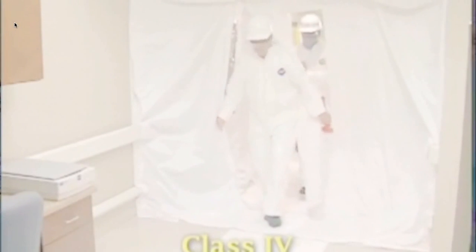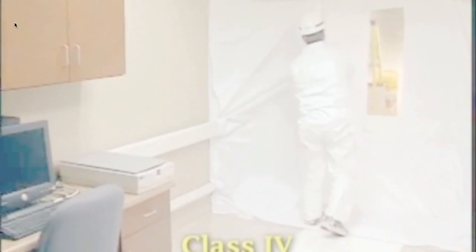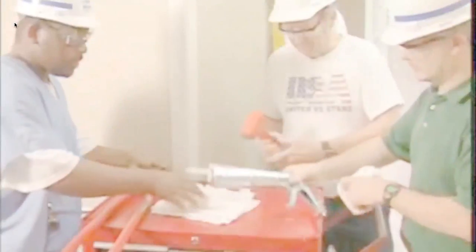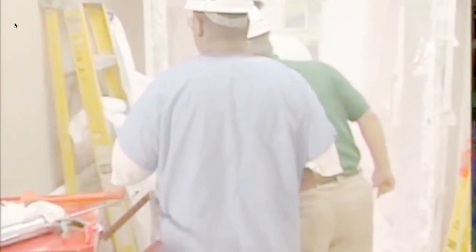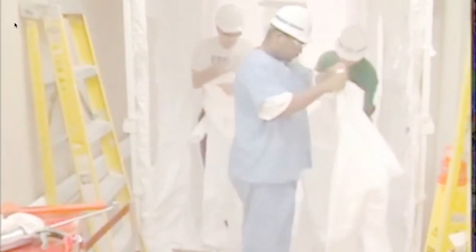This requires careful planning to create containment barriers without creating a hazard, and the possible need for an anteroom so that workers may enter, leave, and change clothes without contaminating patient areas. Anterooms also facilitate waste removal and tool storage. Dust and debris can also leave a worksite on tools. Tools and equipment should be either damp wiped or vacuumed before exiting the worksite. Since clothing can also carry dust, the ICRA should address how clothing contamination will be controlled. Clothing must be free of dust and debris before leaving a work area and entering a clean zone.